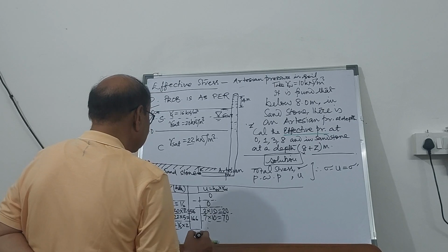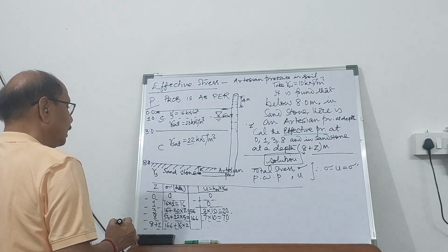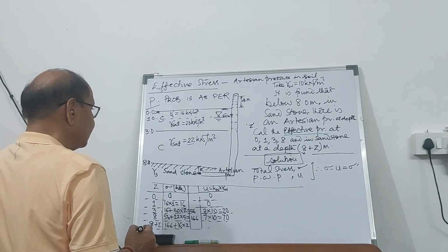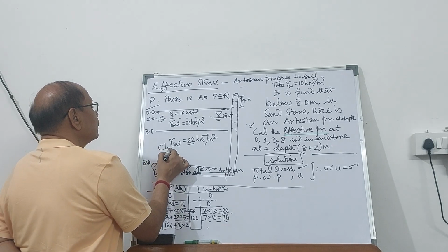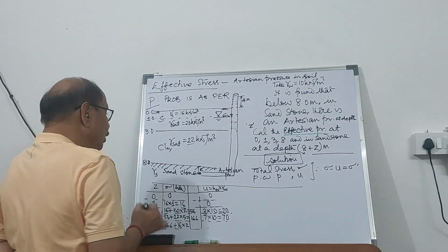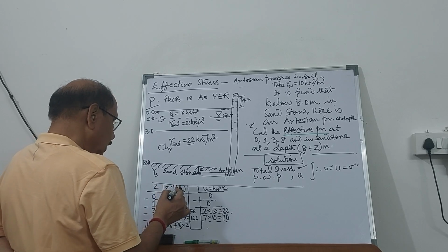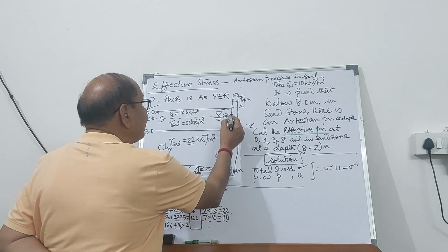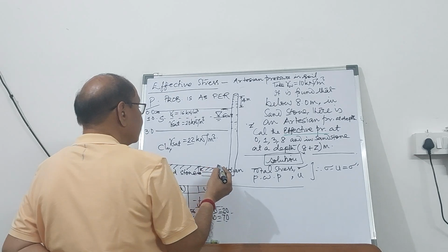So pore water pressure at 8 meter is going to be 70. It is going to be clay, C for clay. S for sand. Now, if you go below, in the sandstone, now the pore water pressure, if you put a standpipe, it shoots up by a further 4 meter.